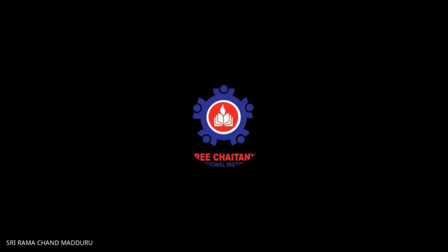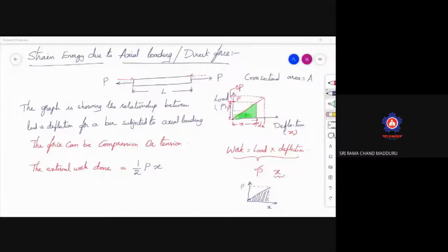So when you are externally applying a load, the corresponding deflection is nothing but X. Now, what happens here? When a body is subjected to certain deflection, it will be having energy. So you can equate the internal strain energy to the external work done. Write down that one.